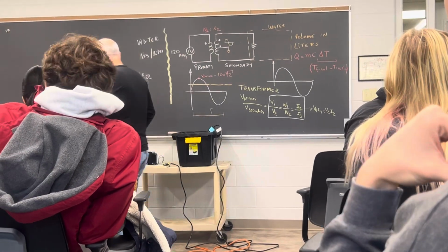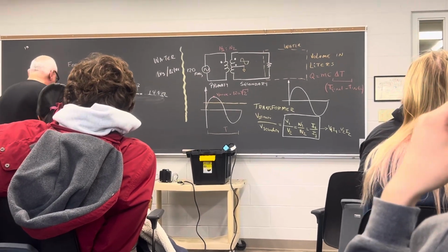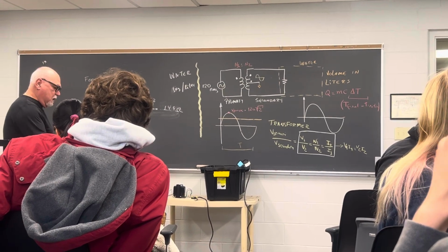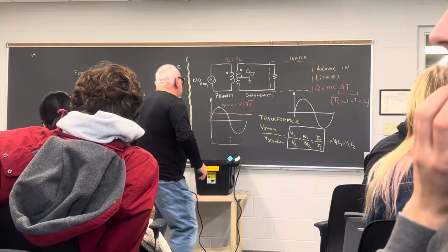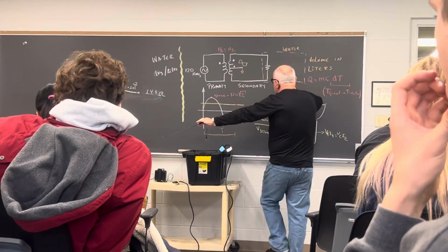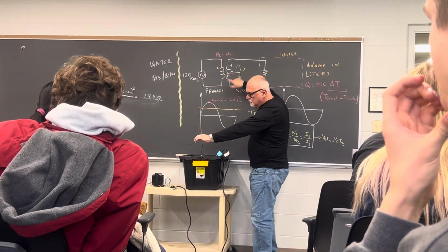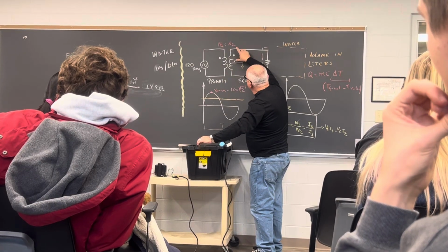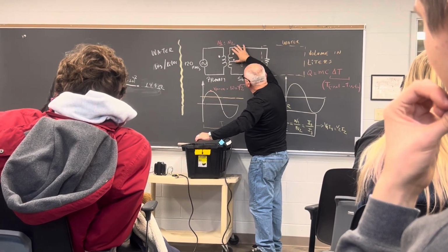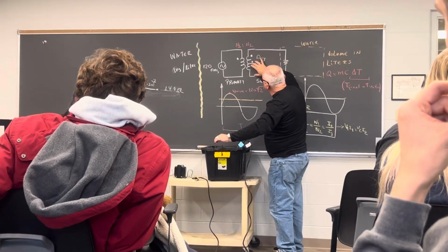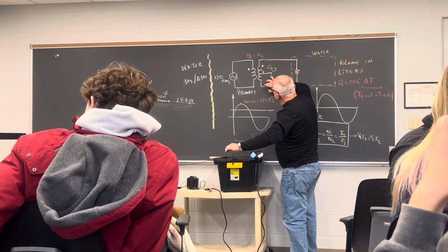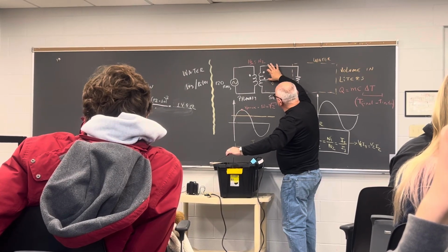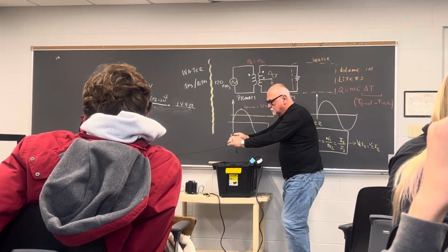How can we start looking at the voltage? The oscilloscope should be more familiar because I've been using the oscilloscope. So I'm going to take the probe and connect initially. See, there's a center tap here. The center tap is the middle of the terminal. I will have the secondary from here to here. This is half, okay? We have 30 volts from here to here and 15 from here. So I measure initially from this center tap to here. I'm going to do it.